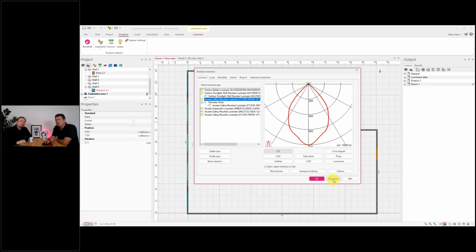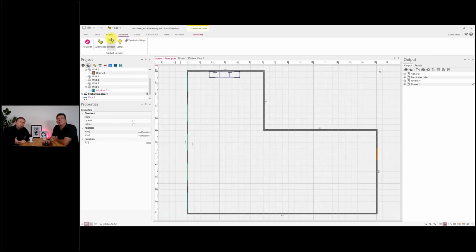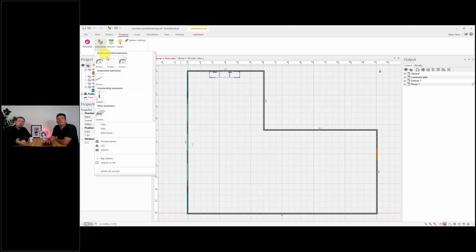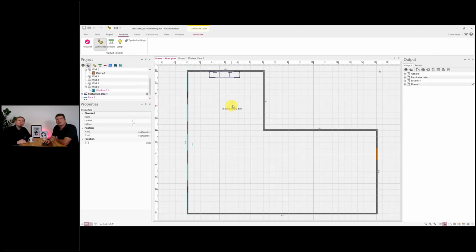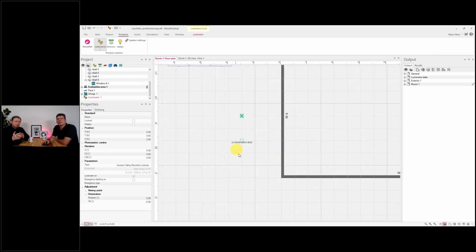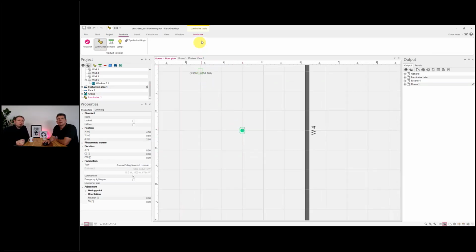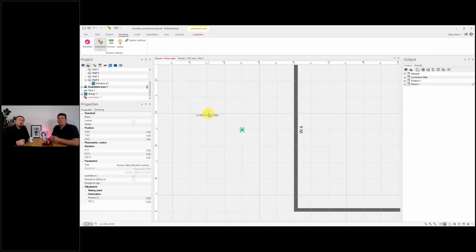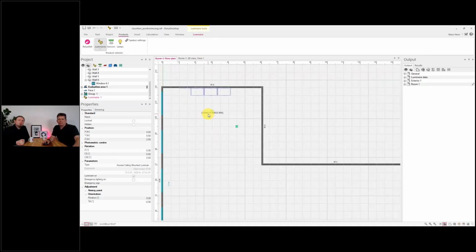Yeah. So the simple geometry you get if you just import an Eulenblatt file or an IES file, and you end up with a simple cube box or a cylinder, and there's no more information on the geometry. But with the complex geometry, the manufacturer has really created a 3D model of the luminaire with a bit of effort. And with this complex geometry, we can simulate the joints and the moving parts on the luminaire quite well. And this is going to be demonstrated.